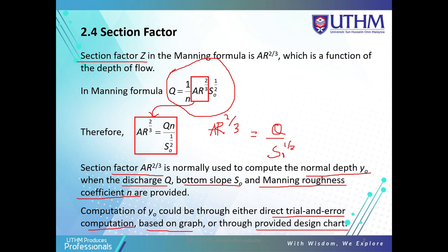So if in your test or in your final they ask you to state or list three methods to get normal depth, you can mention these: direct trial and error method, based on graph, and provided design chart. So these three methods are used to compute the normal depth.